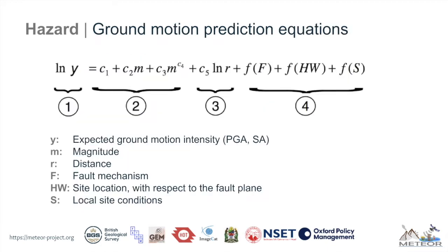To estimate ground motion fields, we often use ground motion prediction equations, or GMPEs. Ground motion prediction equations take information about the source, the source to site distance, and the site to estimate a distribution of ground shaking at the surface of the site given a rupture event.